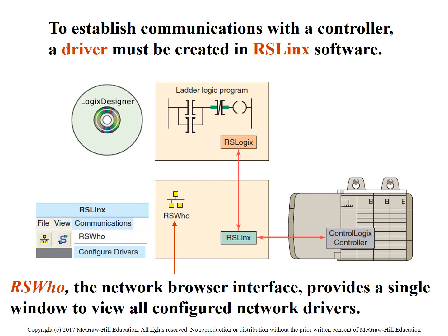It's just not as prevalent as it is in the SLC 500, where you'd have to open up RSLinx to get any communications going. Here, they give you a lot of those tools right in the software, so you're not having to open up a second software. Still, on occasion, you'll end up in a situation where you may have to create a driver to talk to a new PLC that you haven't talked to before, and that's where RSLinx would come into play as another software package.